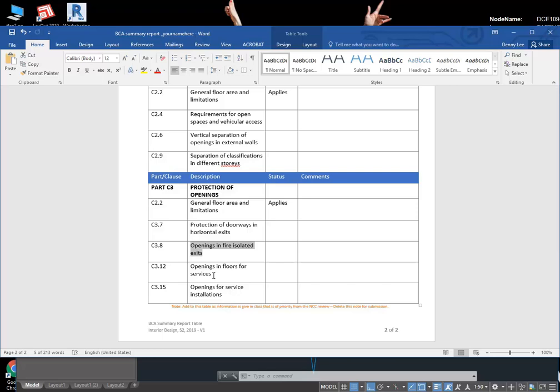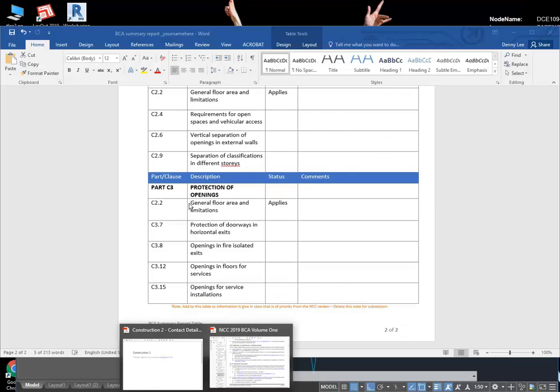No, God no. But my whole building is like what? You've got to change it to fire rated, even if the actual stair has its own fire isolation. Oh, if the stair's got a shaft and then there's a door, yeah, that's okay. Well, that could be okay. Still check, but yeah, that probably is okay. You've got to go through that section, and okay, so it's C3.8.